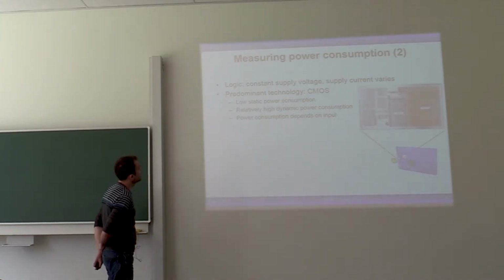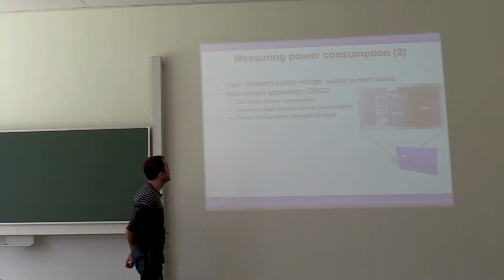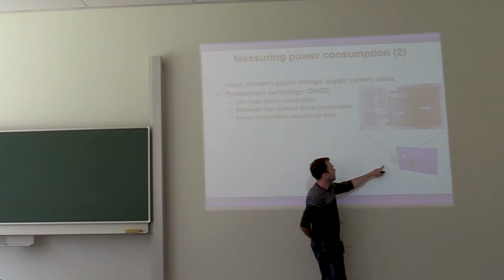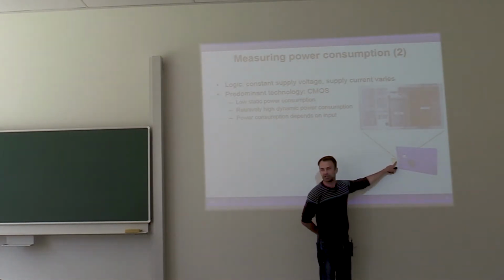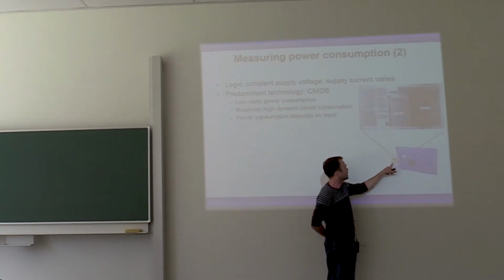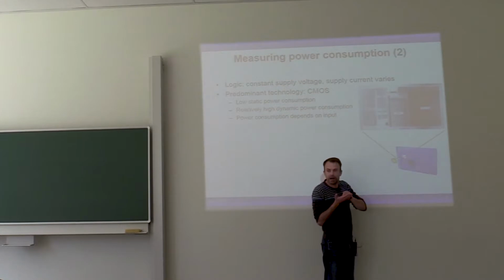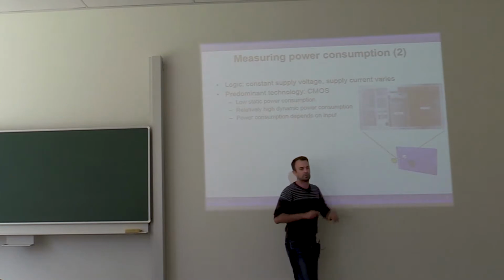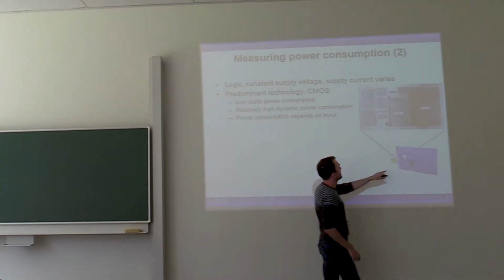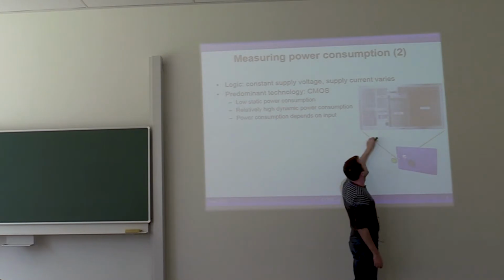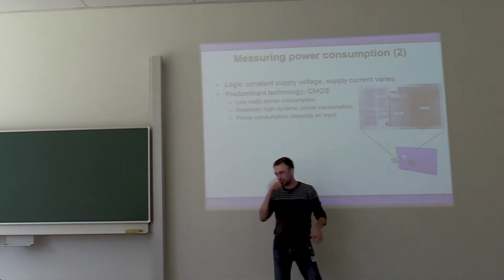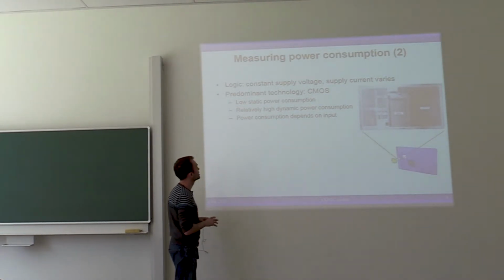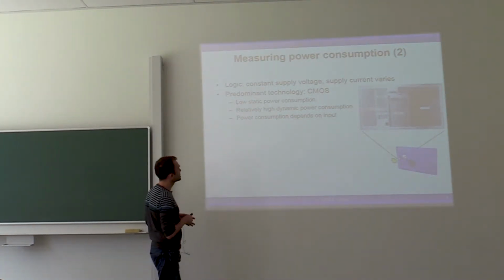As I said before, CMOS is really the predominant technology. Everything is made from it. If we open up a smart card, many people think that the golden stuff that you see is the chip. It's not. It's just contacts. The chip is much smaller. It's only below the middle part of those golden contacts. Lots of it is just plastic to make it into this format that we like. And this tiny chip, if you zoom in on it, you get an image like that. You see different regions, there's memories, there's logic, and so on. And this is built in CMOS.